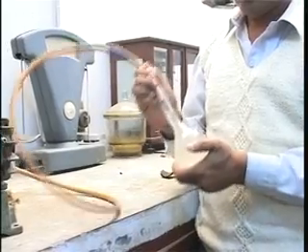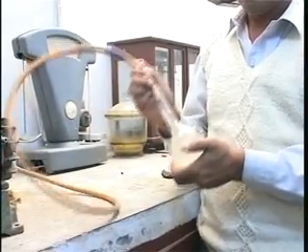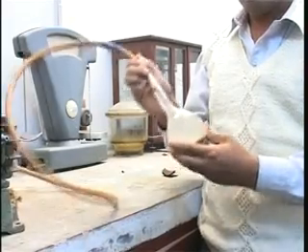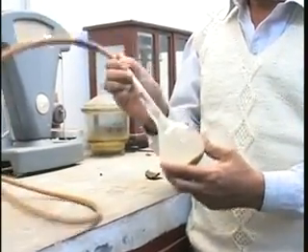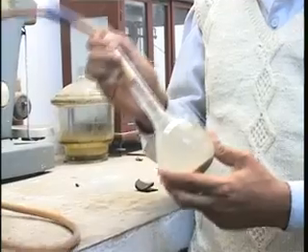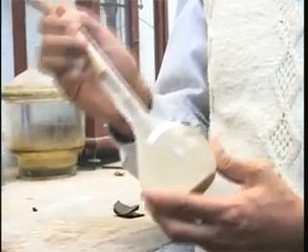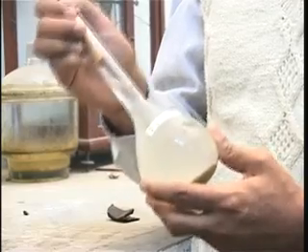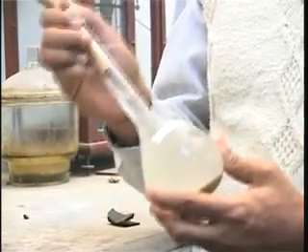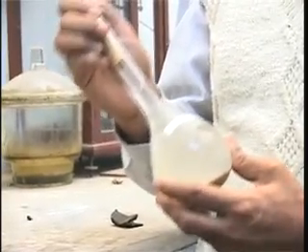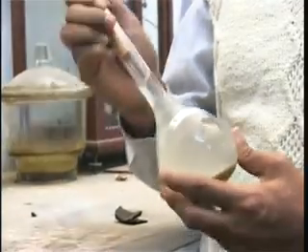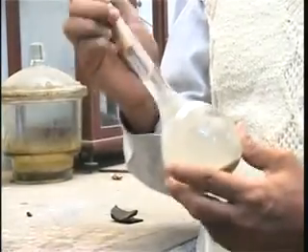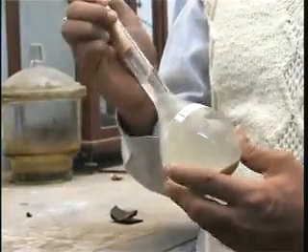Okay, so here you see that the soil is kept under a vacuum pump, kept under vacuum here, and that is being shaken by my colleague here so that the mixture doesn't have any inclusion of air, because that might actually, as I was mentioning, introduce some error in the estimated specific gravity of solids.